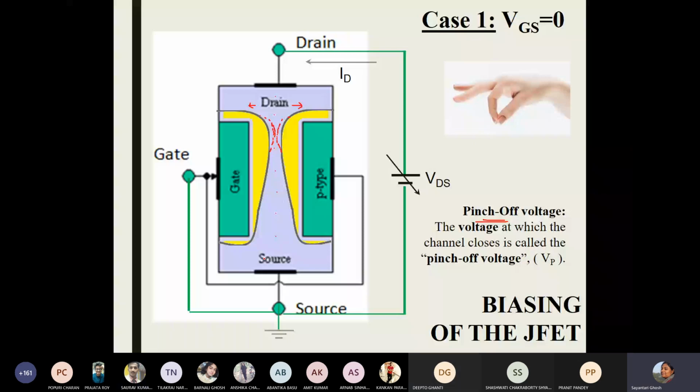The reason for the depletion regions to get formed is this VDS only. If you don't have any current in the circuit, you don't have the entire picture of variable channel resistance and different voltage drops at different points, which makes the asymmetric picture of the depletion region. So this pinch is opening and closing very fast, the gate is opening and closing very fast, maintaining a constant current.